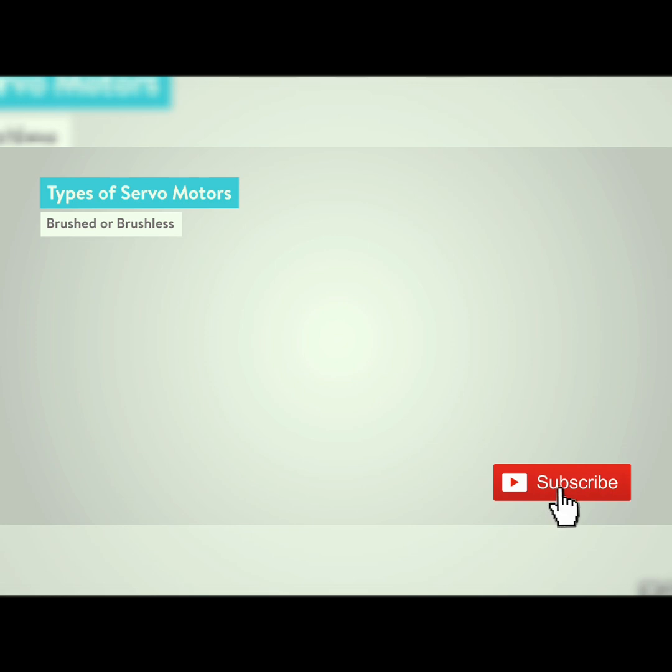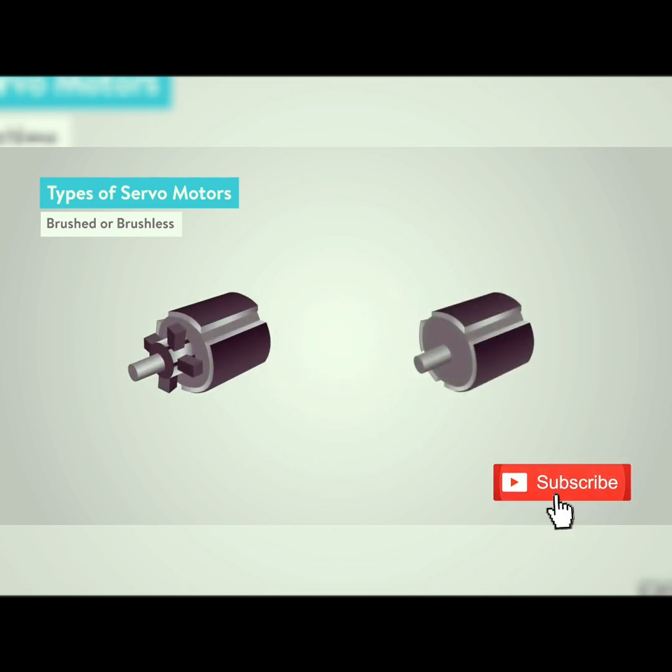Brushed or brushless is the next step. A DC servo motor is commutated mechanically with brushes using a commutator, or electronically without brushes. Brushed motors are generally less expensive and simpler to operate, while brushless designs are more reliable, have higher efficiency, and are less noisy.